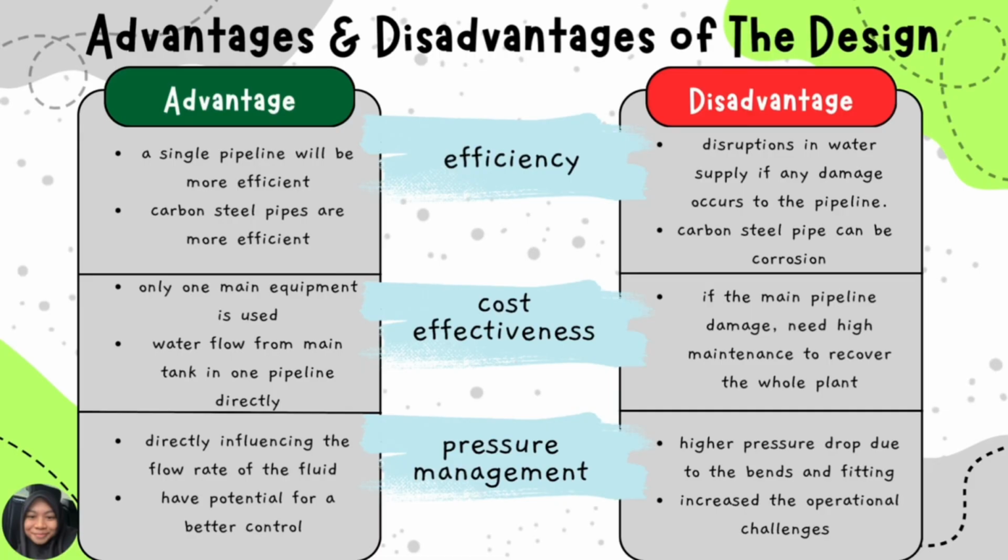Lastly is the advantage of our design based on pressure management. As our design consists of an elevation that has a higher pressure, it can influence the flow rate of the fluid directly and has potential for better control. However, the disadvantage of our design is higher pressure drop due to the bends and fittings, which causes head loss and increases the operational challenge.